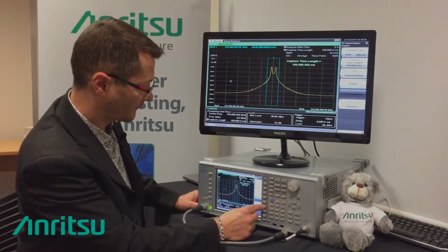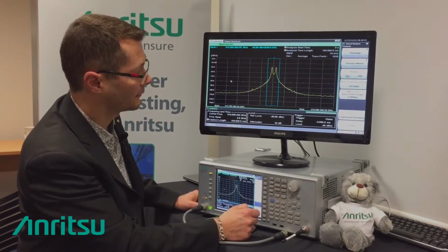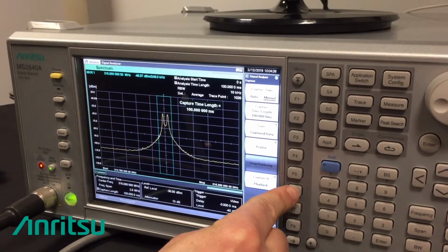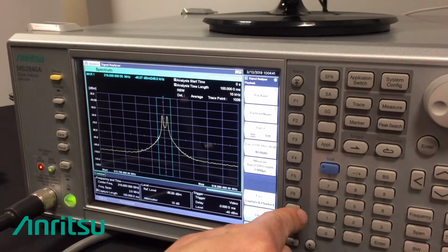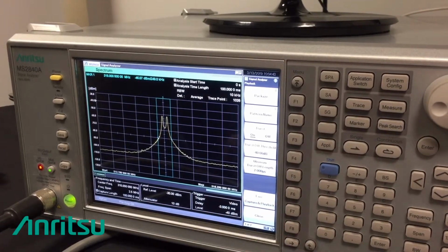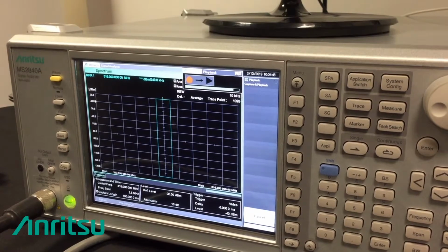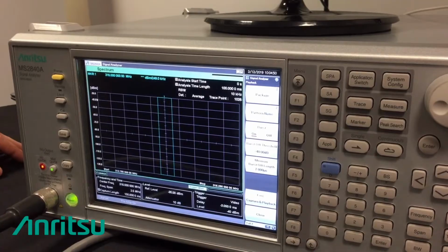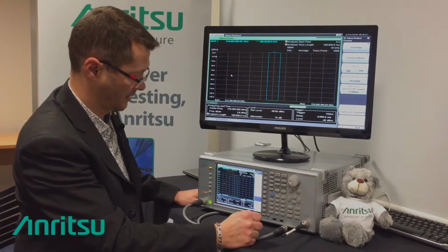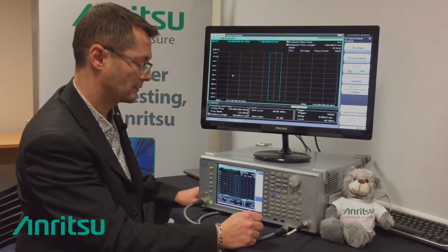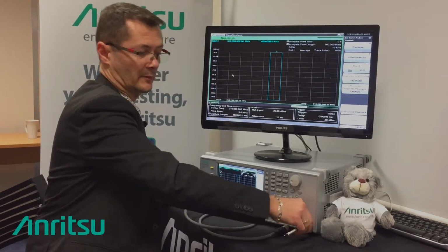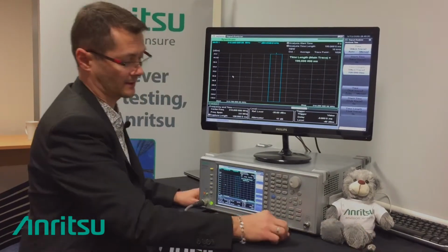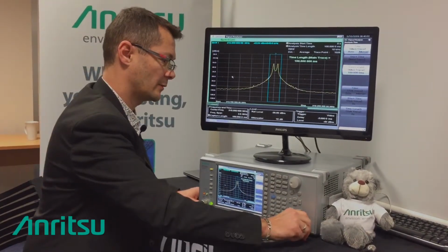capture and playback function. I will not take care at the moment about the name that will be given to the file. It will be time-stamped, and I press the execute capture and playback function. Now it does the job on its own, which is quite easy and not time-consuming. Now it's done. The VSG is ready to generate physically the signal, and then I will forget about my antenna and just replace the antenna by the VSG.